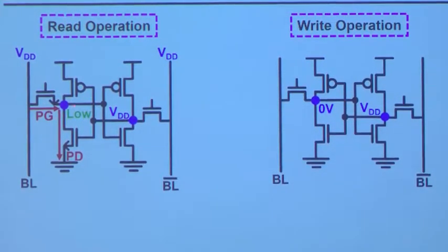And basically what we want is for the bit line on the side of the cell that has low voltage stored to be pulled low when you read the information. That means that this N-channel device has to pull down this bit line to a low voltage through this pass gate transistor. Now, when these devices are on, it's sort of forming a voltage divider. You just want to make sure that the voltage here is low, so it's not high enough to trigger this inverter to flip.